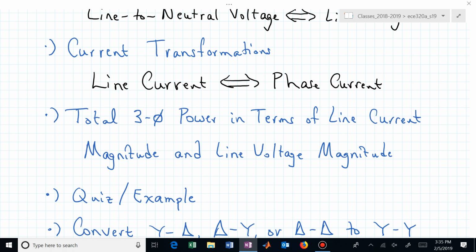We will also have to know the power factor, or the angle between the current and the voltage, but we can now just have access to this terminal voltage measurement, or line voltage, the current in the line, those magnitudes, and then we'll be able to determine through this expression the total three-phase power.